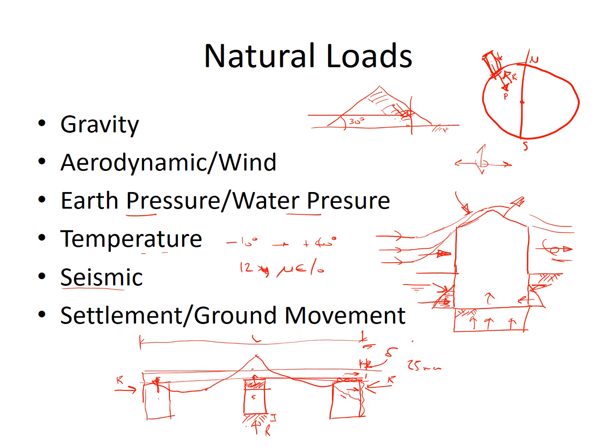So instead of being a continuous beam over this central support, this beam reconfigures itself to becoming a simply supported beam that's only effectively supported at these 2 ends.